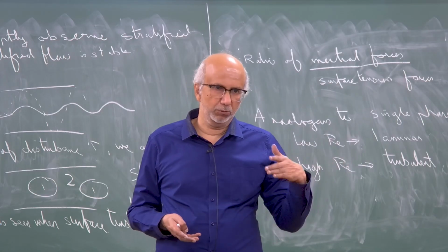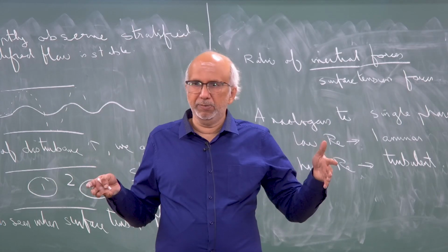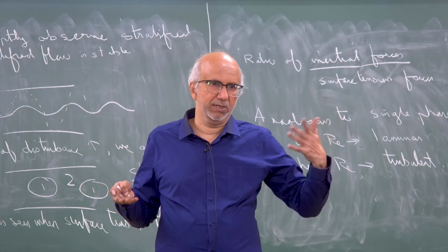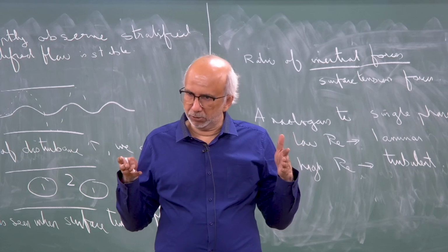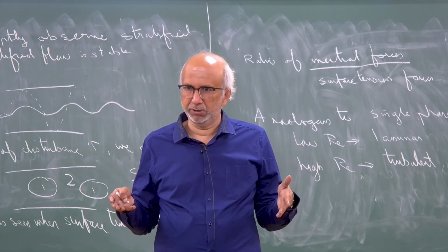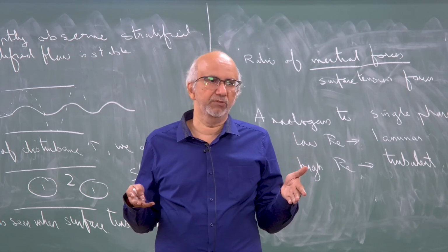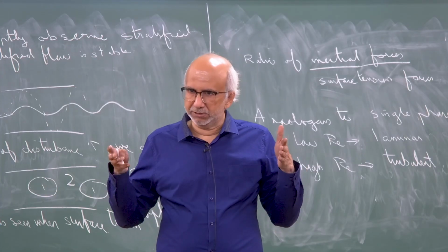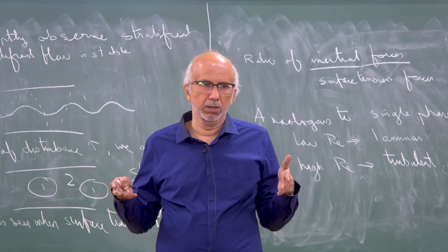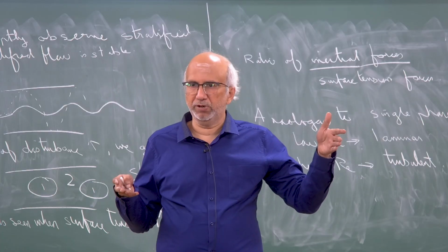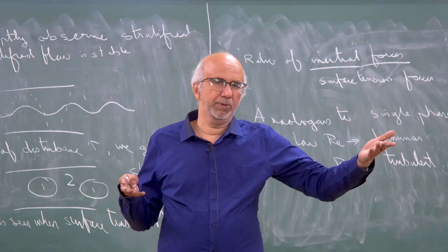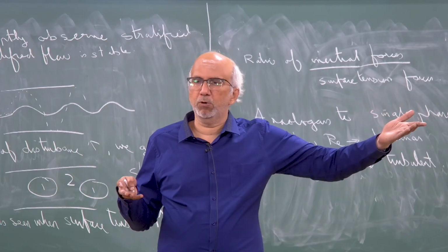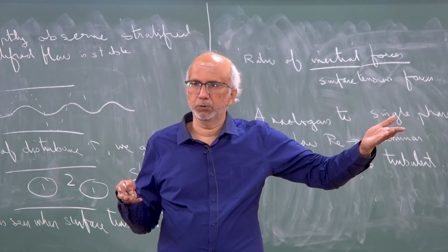But experimentally you do not see the parabolic profile if the dp by dz is very large, because the velocity becomes large, your Reynolds number becomes large. So, although the Hagen-Poiseuille velocity field is a possible solution, you do not experimentally observe it, because that is unstable. Beyond Reynolds number 2100 it becomes unstable, and what you see is turbulent flow, okay.